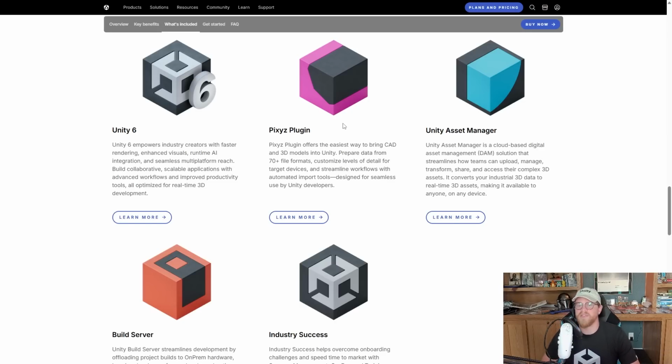So the cool thing here is that it also has some automated workflow steps that you can take, where if I have found 15 different things that I want to do to an asset after I import it, like moving pivot points, reversing normals, decimating based on a query of metadata, I can do all of that, and I can create a rule set that will automatically run that sequence of rules the next time that I import that asset.